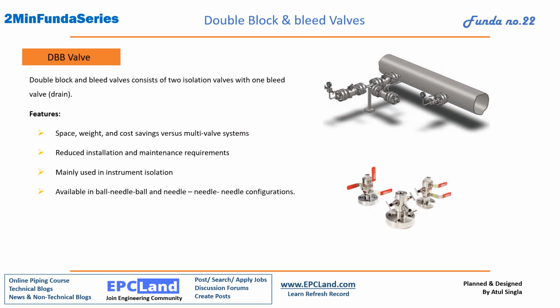Reduced installation and maintenance requirement. This is very small, very easy to install, and maintenance is very simple. Mainly used in instrument isolation and available in ball and needle configuration. So this is a very simple concept which we generally use for isolation, actually double isolation.